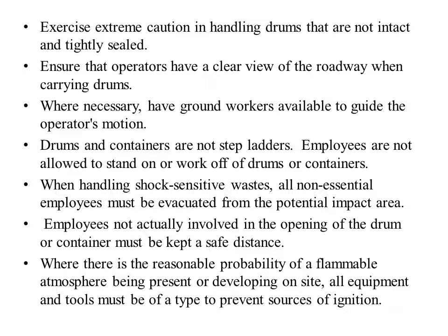So next point, when there is a reasonable probability of a flammable atmosphere being present or developing on site, all equipment and tools must be of a type to prevent a source of ignition. So wherever there is a probability that this particular chemical may cause fire on site, then we should make sure that whatever equipment and tools are being used during that time should not be a source of ignition. The equipment and the tools should be such that they prevent sources of ignition.